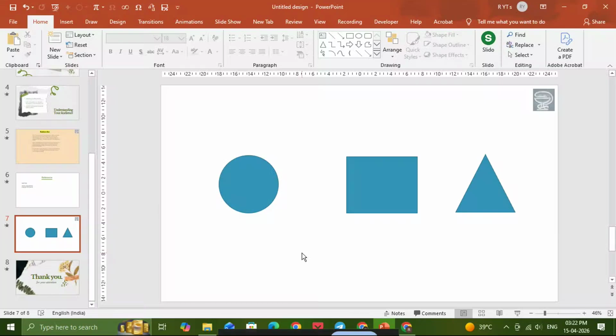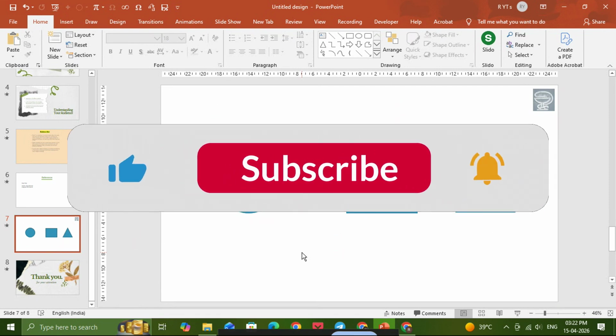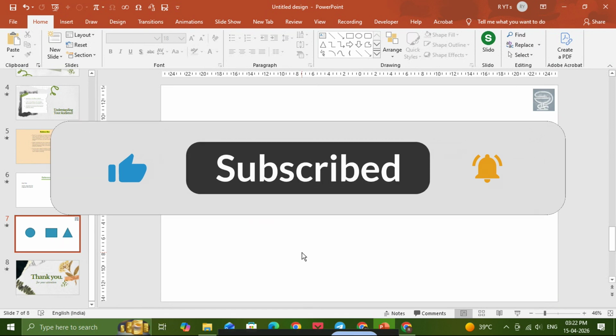If you want cleaner, more professional slides in PowerPoint, this video is going to show you exactly how to use the grid and alignment tools for precision. These features are perfect when you need your text boxes, shapes, icons, and images to line up neatly without guessing or constantly dragging objects around. By the end, you'll know how to turn on grid lines, use guides, align objects properly, distribute them evenly, and enable snap settings for faster auto alignment.